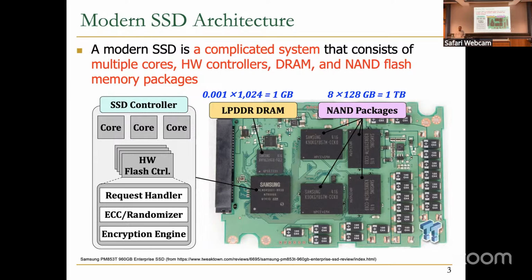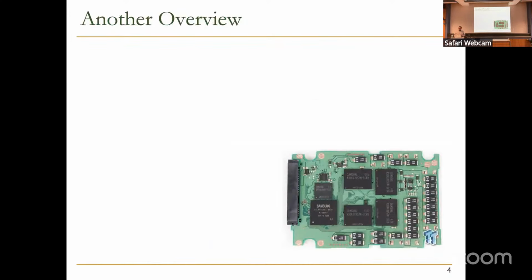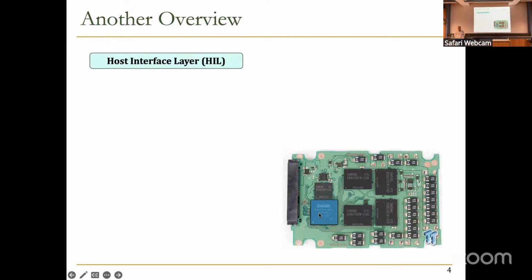Like in the memory controller, in the processor, we don't really have that many components trying to control DRAM. But here in the SSD, there are a lot of things going on to control how flash chips can work. So here is also another view, in which this processor, the storage controller, essentially does a lot of different tasks.